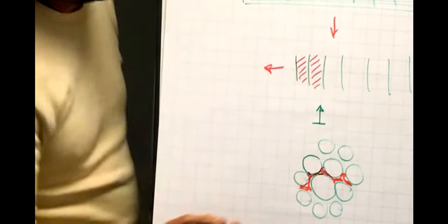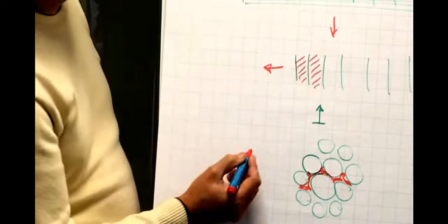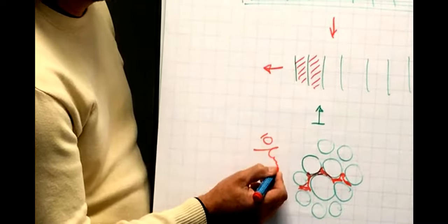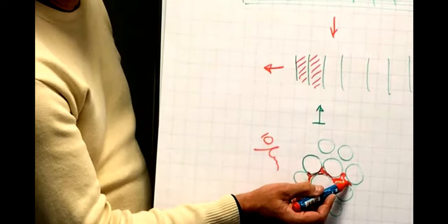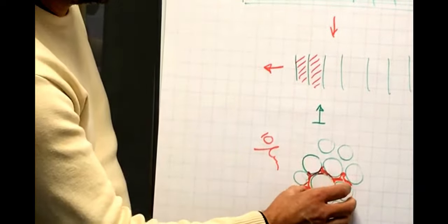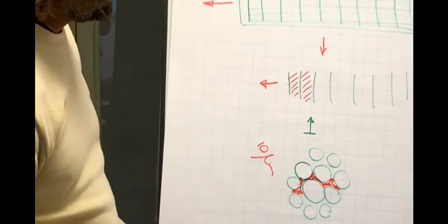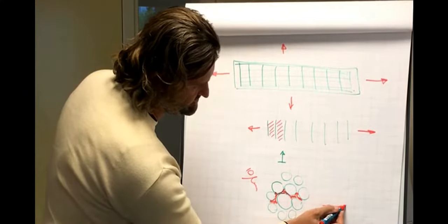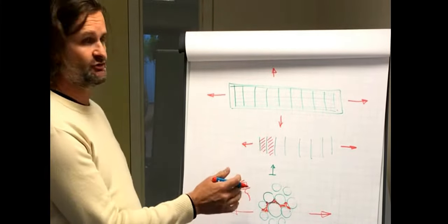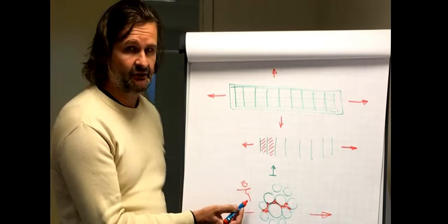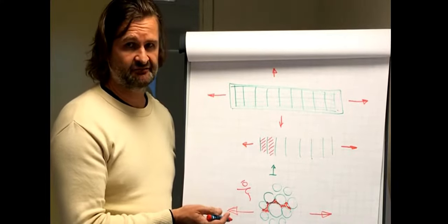See? Now, the diameter of a fiber on average is 10 microns. So you can already see that the thickness of resin is probably 2 microns or something like that. This means that if we want deformation in the same direction, so I'm putting on the same load again, we're asking this layer to deform, and we're depending on the resin to allow for that deformation.